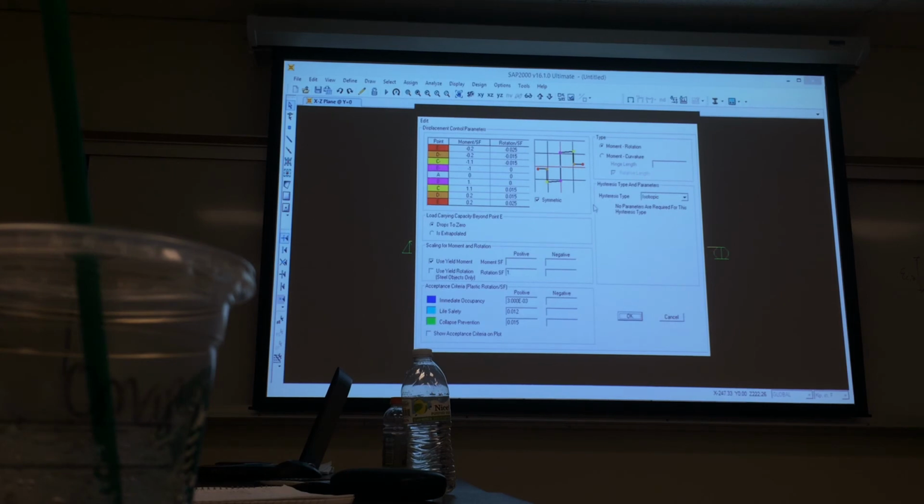There we go. So if you look at these different curves in here, you can essentially give SAP now your moment curvature response in here. So you take that result, and you can tell SAP, I want to form a hinge, and you can assign this hinge to different elements in here. But this hinge then, you basically can look at this stuff in here, and we'll talk about this when we actually start doing a pushover analysis and we put specific values in.